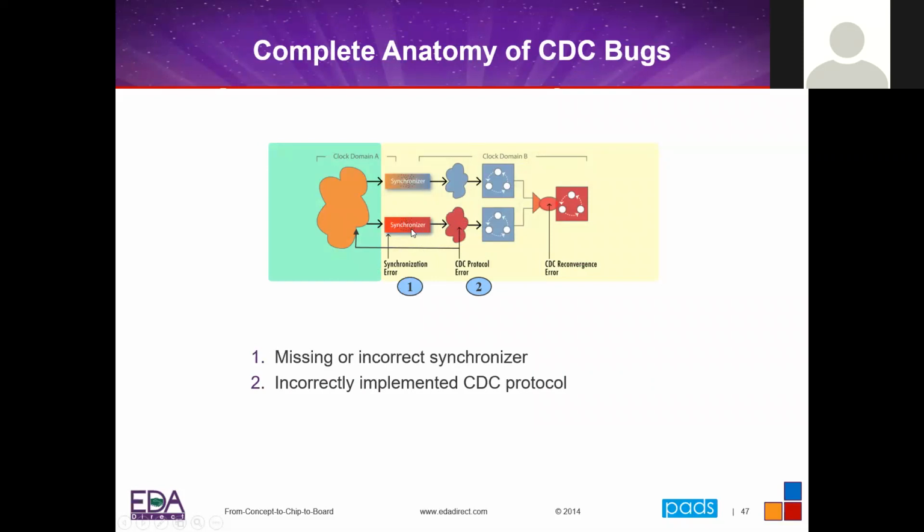Now let's say that I've done the analysis and I say, hey, there's a proper synchronizer here, and yes, I cannot violate that thing. So right here, this one's good. And then I do the same analysis up here and say, yep, this synchronizer is also good. So I've got 2 different paths here. I've proven that both of those paths are okay. But let's look at this.